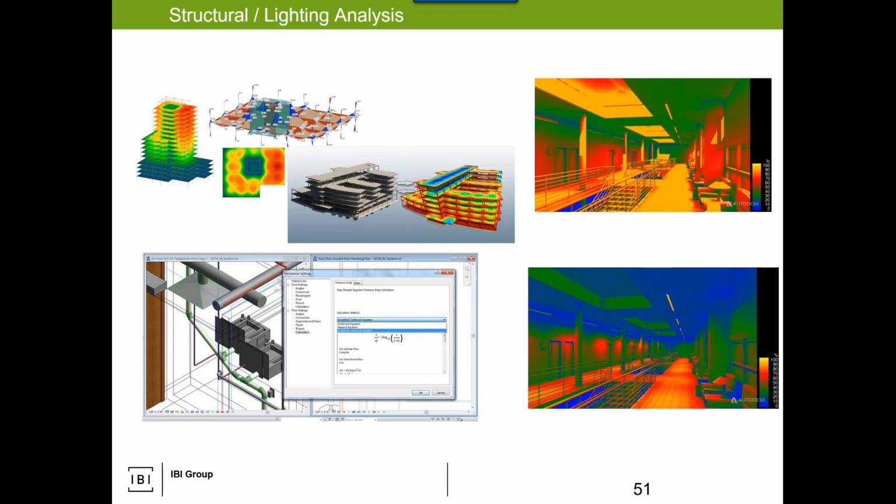Structural and lighting analysis, we do this quite a bit, analyzing deflection of slabs and beams based on loading, analyzing penetration of lights, often daylighting, so penetration of daylighting from windows to the interior portions of your space. Often that's used to prove sustainability requirements. Some of these items, again, the importance: are your modelers calling slabs slabs, beams beams, and columns columns? Are they mixing things up? That would obviously have a detrimental effect on our structural analysis. You may be asked to help facilitate a transition or a translation between the authoring tool and the analysis tool. So some of those items will come into play.